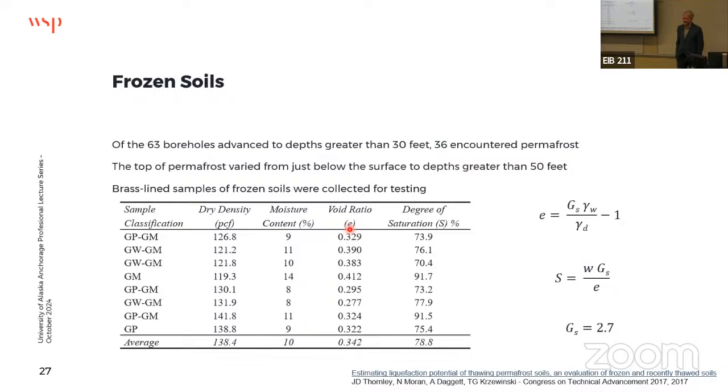So in the earthquake here in Anchorage, where some of the approaches failed, like Minnesota or wherever it was, were those gravels also involved? Well, I worked on the Minnesota off-ramp. So that one, there was peat over top of sand, over top of much denser material, right? At the time, the peat was removed, but the sand was below groundwater level, right? The sand was left in place, and then they filled and built the MSE wall over the fill, but they got rid of the peat, right? So peat, that's good, right?